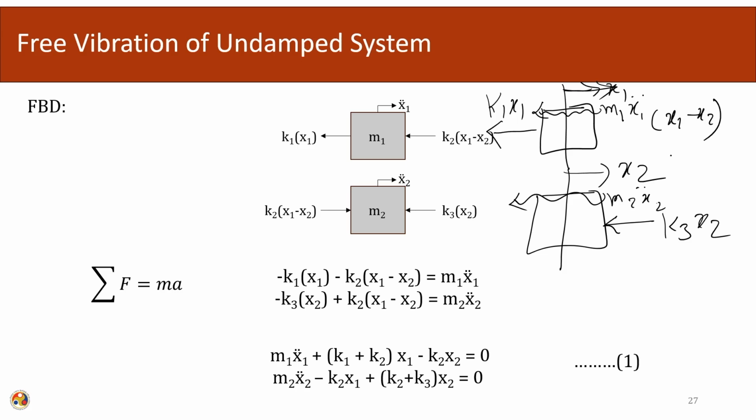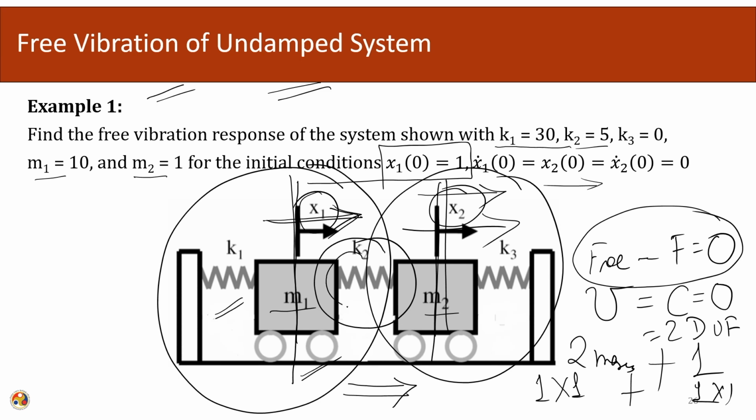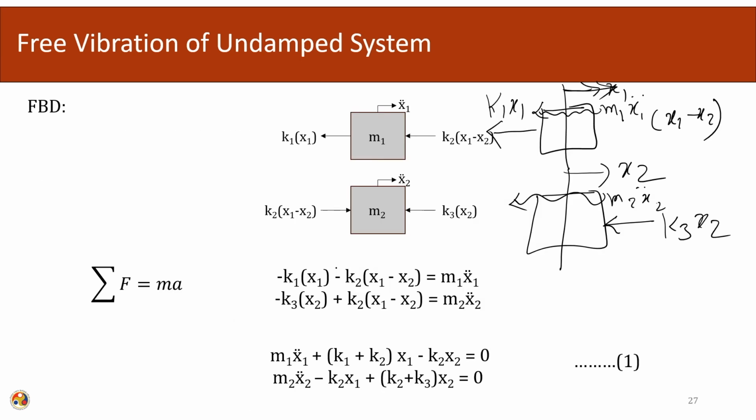And in the first case, this spring is going to oppose the motion towards the right. Okay. So, this is causing it here. And in the second case, on the other side, it will be applied. So, this becomes K2(x1 minus x2) and again K2(x1 minus x2). Okay. So, now we have written down all the forces in the system.